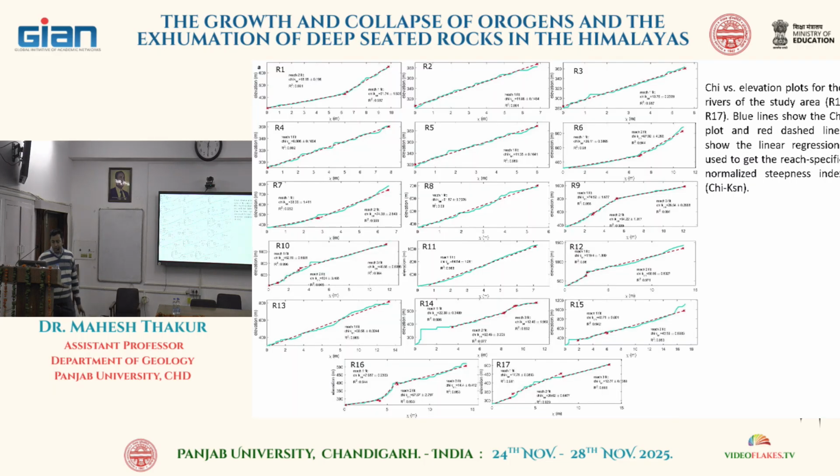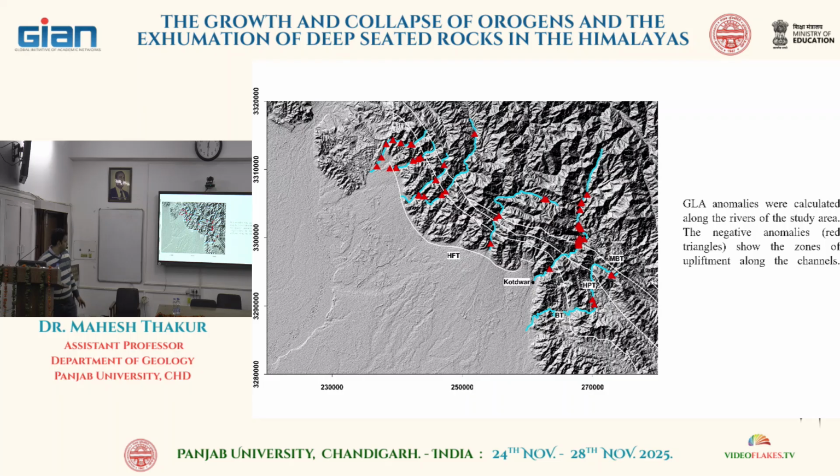So we did some morphometric analysis in this area, and if you see this diagram very carefully, you will be able to see that there are some drainages which are formed in this area. New drainages are coming up. So we proposed that in this area a fault, which is reported, is going beneath these sediments, and this area is being uplifted slowly. If any area is being uplifted slowly, then new drainages are formed in that area. That is because water is the first to know.